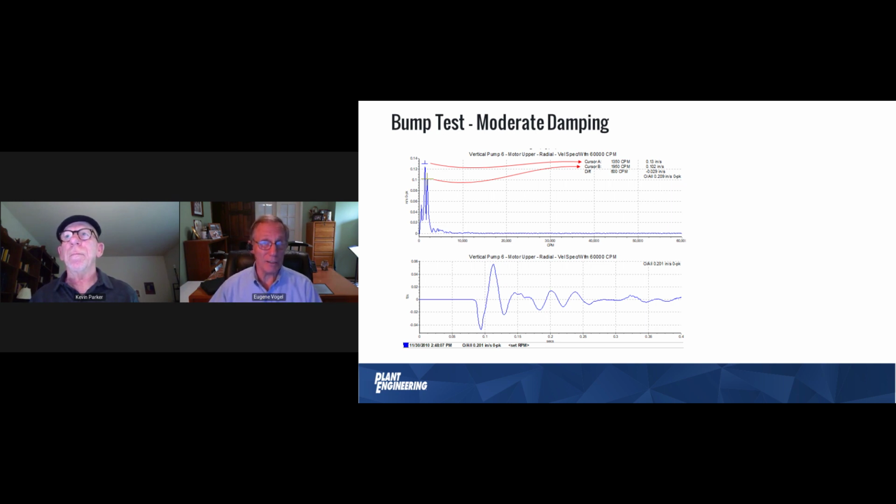I can tell you that's unusual. It's much more common for the fan to be out of balance and the motor to have a natural frequency. So the motor is shaking a lot and the fan's not shaking too much. And everybody's saying, oh, it's a bad motor. Well, it's not a bad motor. It's a bad base. And there's a natural frequency in the base that's letting it amplify the small amount of force that's coming from the fan. It goes through the base and up the other side.